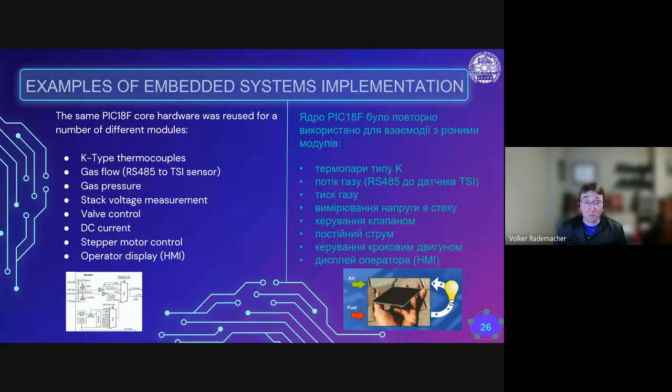However, for the stepper motor, the additional difficulty was that a stepper motor has resonance points where, if you hit exactly this resonance point, you might just fall completely out of step. Meaning the motor will, from rotating at 500 RPMs, within one rotation, drop to 0. And the task then is to avoid these resonance points, to step over the resonance points. Okay.